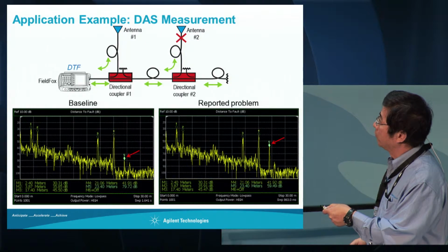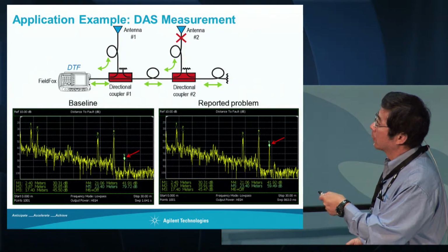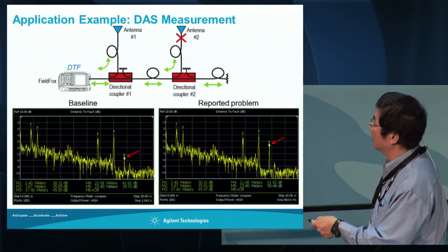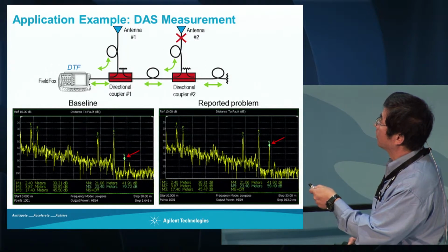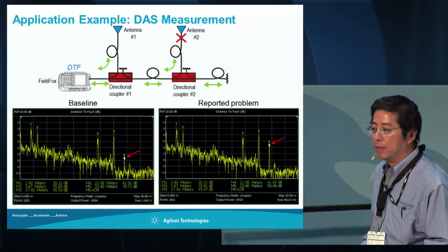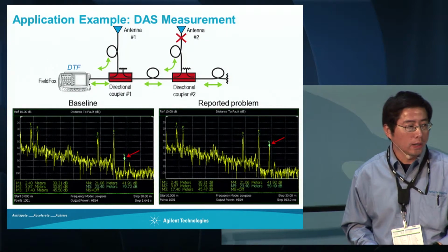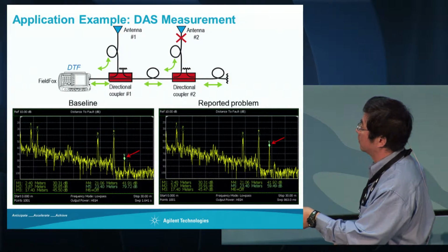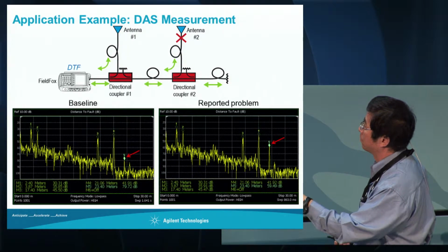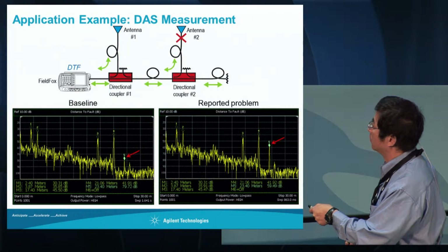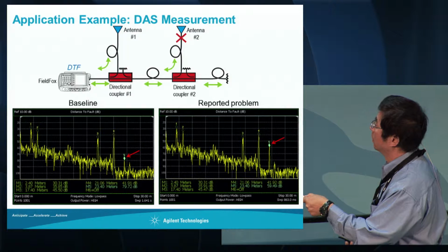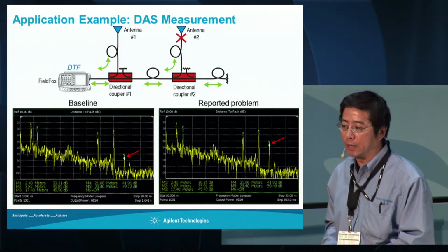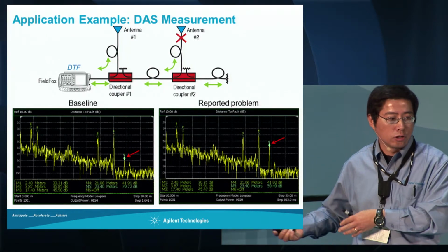We basically take 2 couplers and hook up 2 antennas. You can easily see each one. We can actually simulate whether we leave this one open or connected. So if we disconnect this one, you see the signal going up. That helps the user quickly identify which part is the problem. For example, over here, you can easily see this is the antenna, this is the adapter before the coupler, then the second one, etc. Basically, you've got 1, 2, 3, 4, 5. Of course, in the real situation, it's much more complicated than that. You just have to test one section at a time.